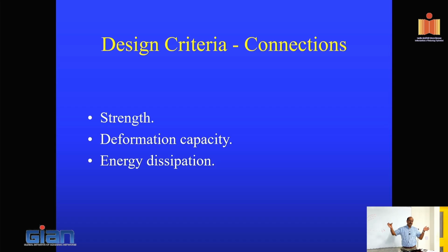Now, we introduced the monolithic or emulation concept. It's changing some of these things because you're changing the behavior. From there, we went to the jointed concept. We are able to separate some of these things, but we need to match. We don't have to necessarily match everything exactly, but you need to quantify and say how much I need. Damping would be a good example. Okay, do I need to produce 20% damping? Can I do less? In this particular case, with the amount of U-plate we put in, the minimum amount of damping that we got was 18%.